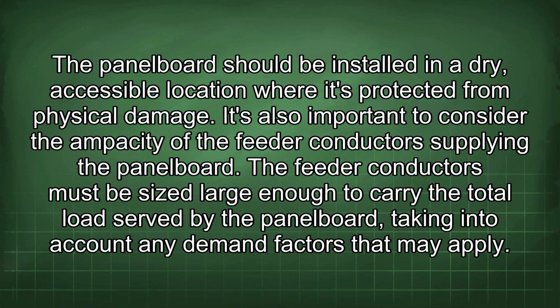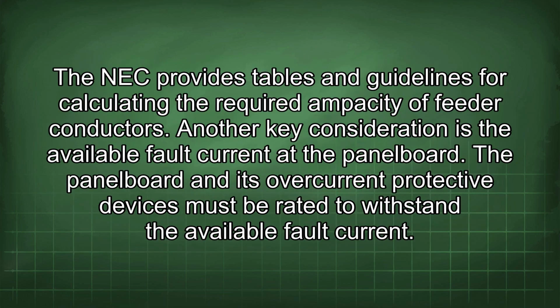It's also important to consider the ampacity of the feeder conductors supplying the panel board. The feeder conductors must be sized large enough to carry the total load served by the panel board, taking into account any demand factors that may apply. The NEC provides tables and guidelines for calculating the required ampacity of feeder conductors.